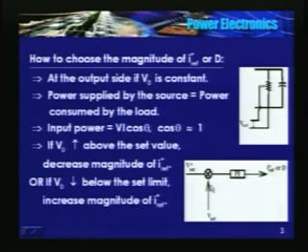This is a broad philosophy. This need not be the actual version here. Just a PI controller determining Iref or D need not be true. There may be additional blocks also. So if you find that V actual is higher than Vref, controller may reduce Iref and vice versa.